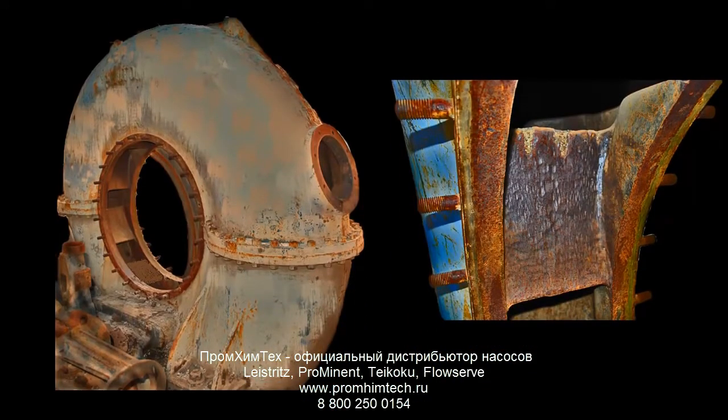This next example is also of a hydroelectric facility. This particular facility dates back to the early 1900s and is now abandoned. This is a picture of a horizontal turbine housing. If we look inside the housing, about here, we can see the results of cavitation and erosion that occurred over the years of service. Also, notice that if you look closely, you may be able to see what appears to be the results of a brazing process repair in a couple of locations that occurred sometime in the past.